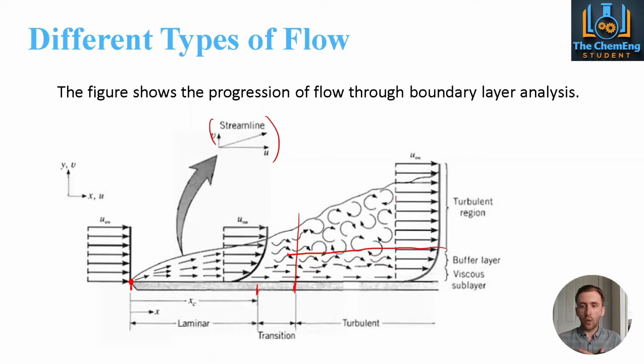And this gives you a wide range of characteristics. For example, it allows us to conduct heat transfer a lot quicker. It's more efficient. It allows mass transfer to take place a lot better than, say, in the laminar region. Now, these circles or arrows, these can often be referred to as eddies. And you can get very large scale eddies, for example, a hurricane storm, or you get very small eddies like the vortices in, say, a river, for example. But that's the technical name for these types of systems.